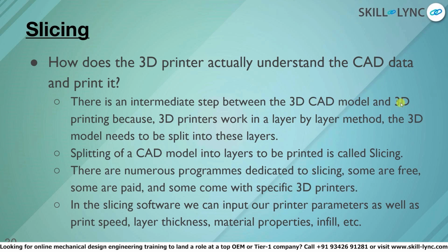But let's see what we've discussed. Okay, so we've discussed that it's an intermediary step between the 3D CAD model and the 3D printer. How the slicing software splits the CAD model into the different layers. There are numerous programs. Okay. So you can input the different parameters into the slicing software like print speed, layer thickness, material properties, infill, temperature of the printed head, many different parameters. You would need a whole separate course just to cover slicing software in itself. This is just a basic overview.